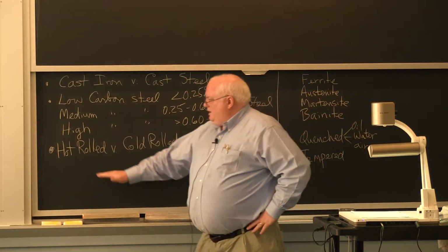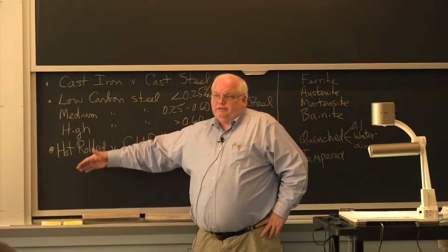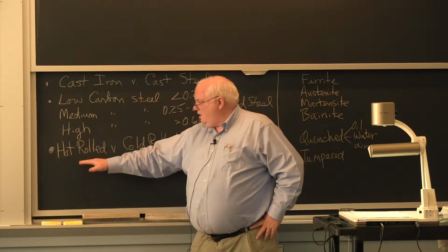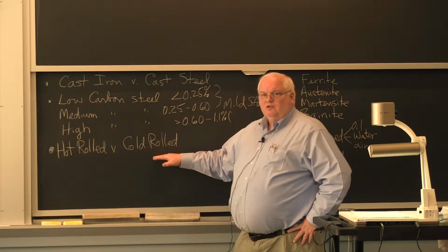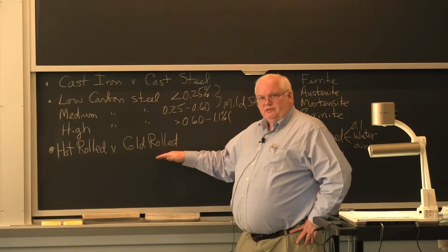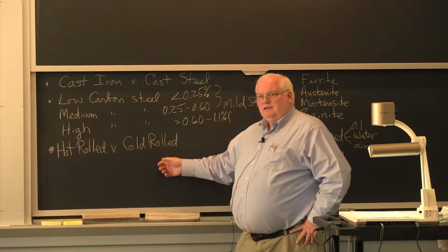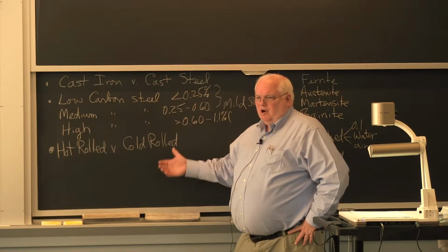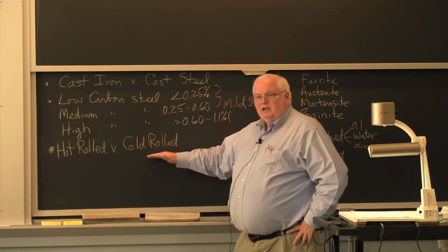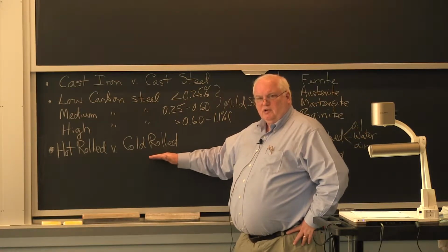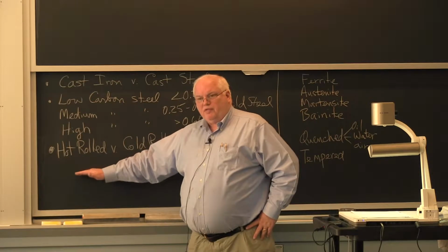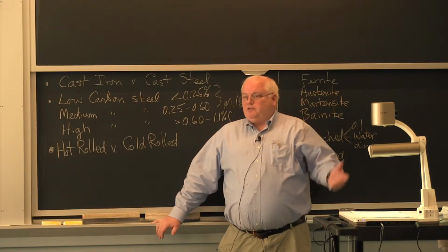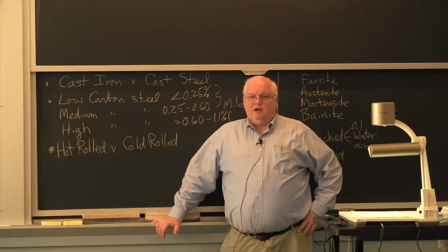Hot rolled comes out annealed, and so the strength is 200 megapascals, 35 KSI. Cold rolled, you can come out with different hardnesses, and we sell it in the annealed condition, the half hard condition, or the hard condition. You can get 100 KSI out of a low carbon steel in the cold rolled condition, whereas you can only get about 35, 1/3 of that, in the hot rolled condition, and it's a function of thickness coming out of the mill.